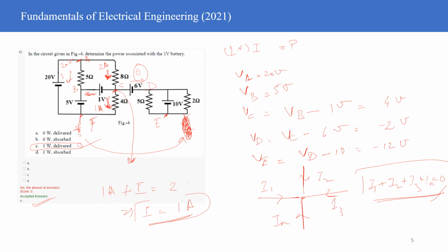So the same thing is happening over here as well, Hassan. You have the node C available with you, and from the node C, 4 currents can flow. One can be 2 ampere, one can be this I current, one can be the outgoing current as 1 ampere, and one current is flowing over here. This current we know as 0 ampere, right, Hassan?